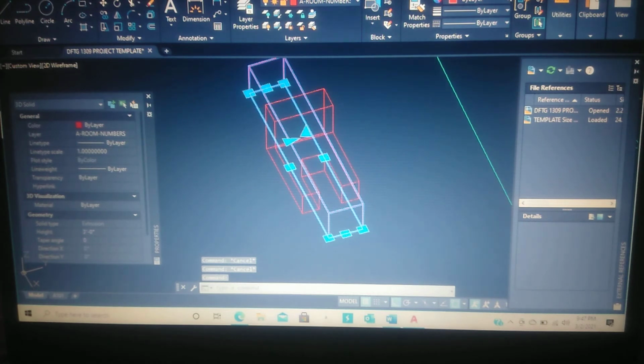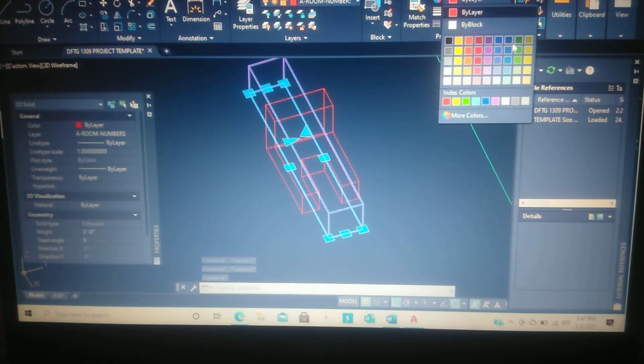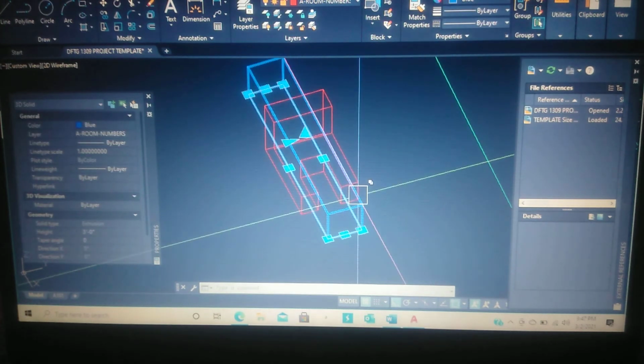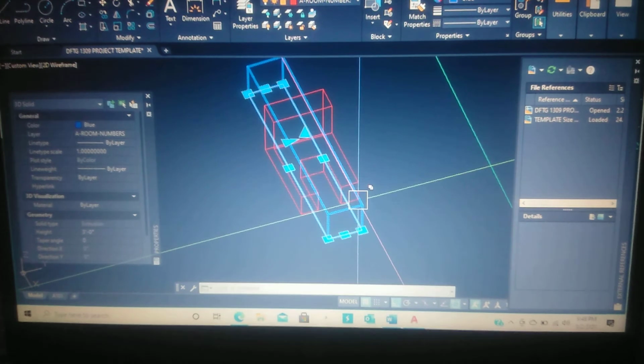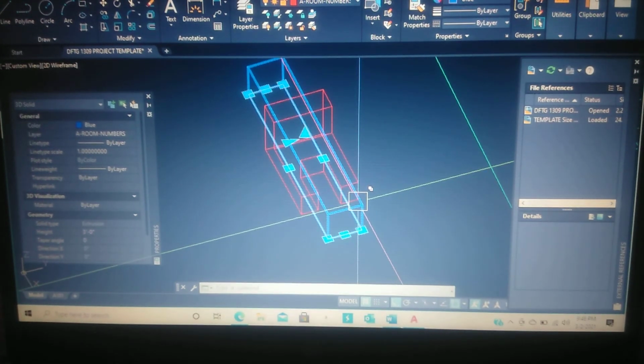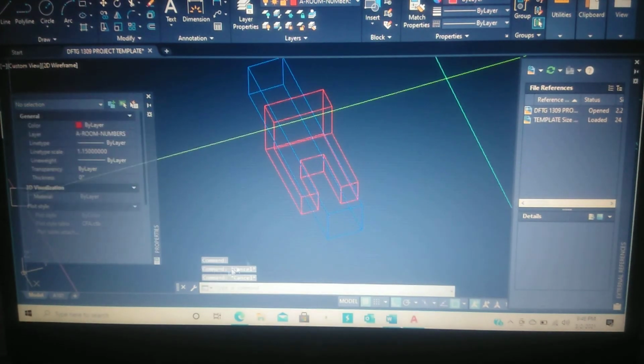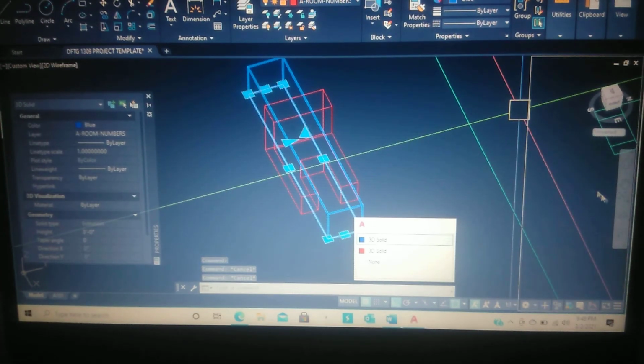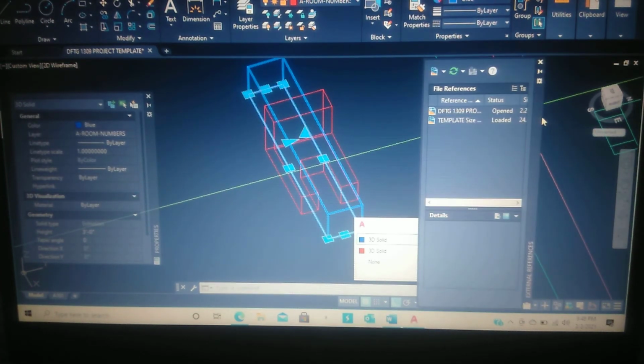Let's go ahead and give it a different color now. Because what's going to have to happen is we're going to need to change views to actually move the rectangle into position where we can actually do the 3 by 1 inch deep insert. So you want to come here, select the object, and there is a view cube right here. And when you're not using the X reference palette, you can just turn it off.